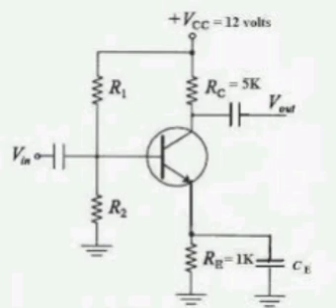Then the IS is parallel with RS is parallel with RF and given to base of the transistor, and the collector is given as RC1. The emitter is given to RE. The emitter output RE is given to the base of the next transistor, and then the emitter is grounded. The collector is given parallel with RF, and RC2 is also parallel. The output is taken as V0.